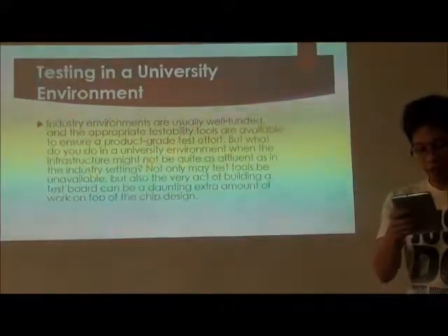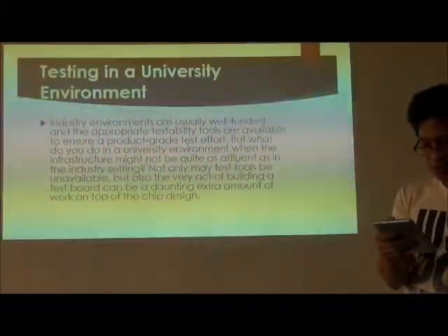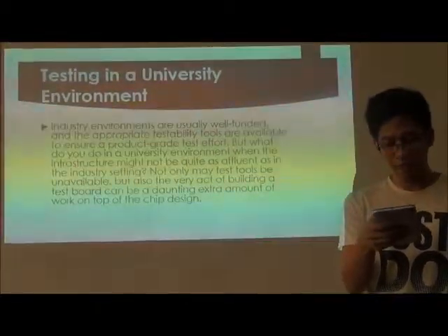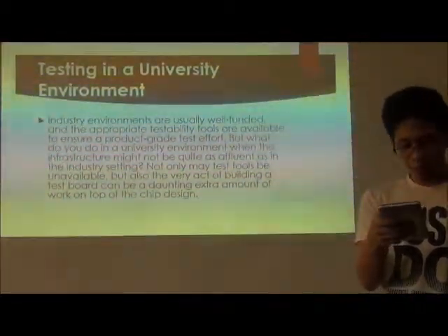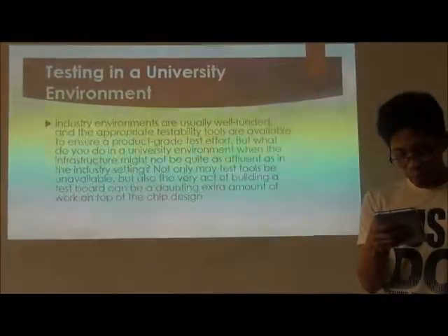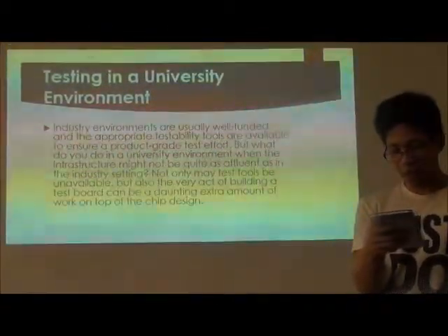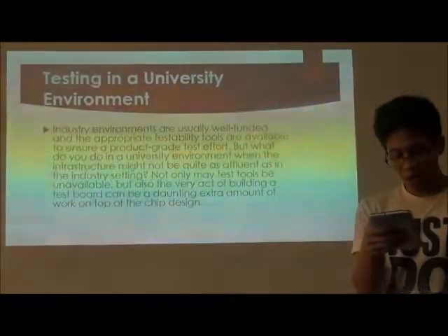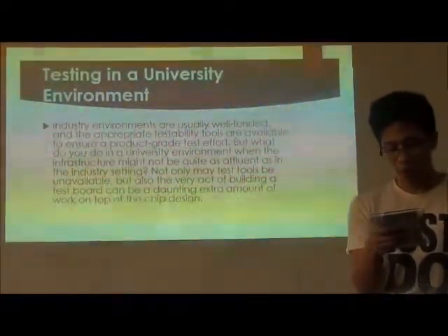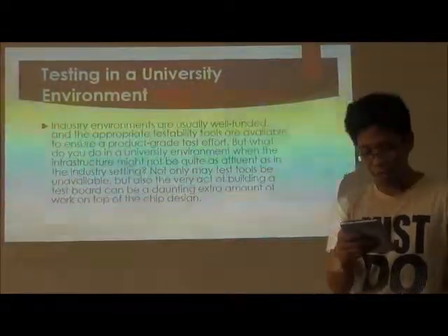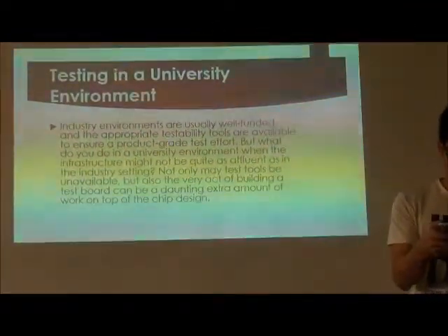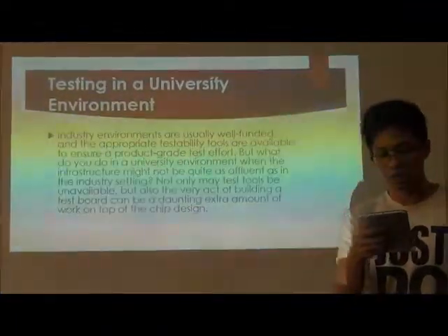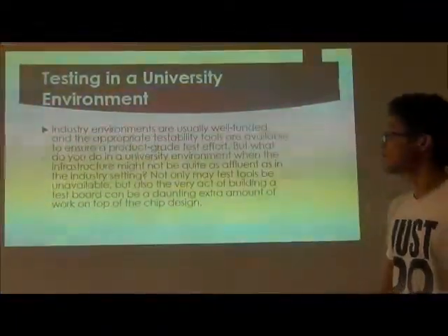For a start, the integrated environment available for most IC design flows allows the designer to simulate the test circuitry. So while it might be seen as superfluous to the test at hand, including test circuitry can save a huge amount of effort after the chip returns. Moreover, on-chip circuitry can often test at speeds that are impossible off-chip without extremely expensive production test machines. The main point is to think ahead.